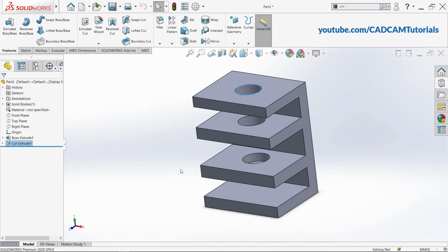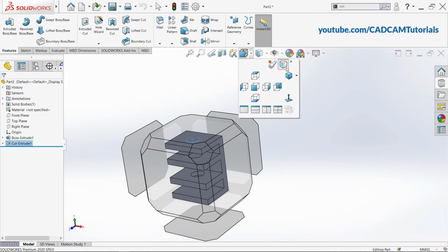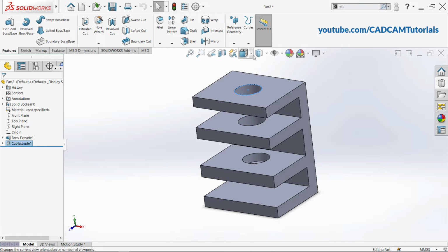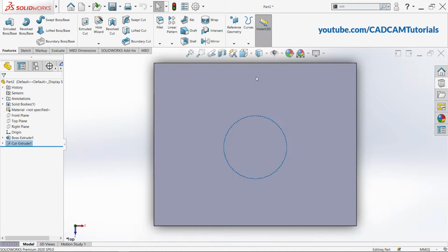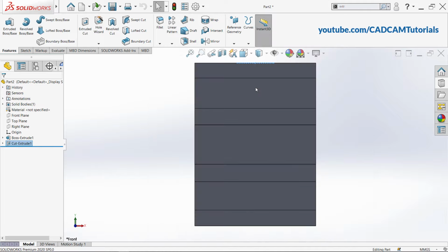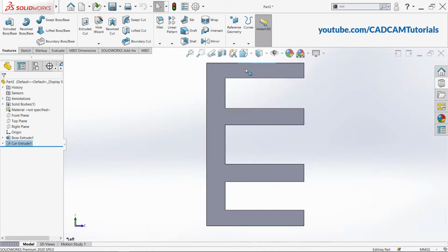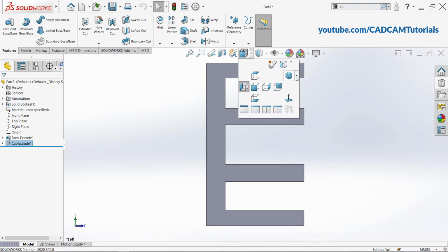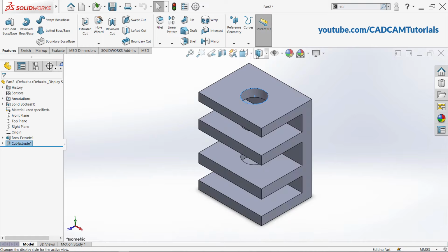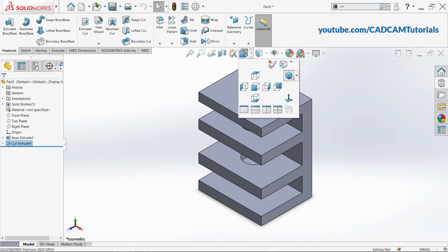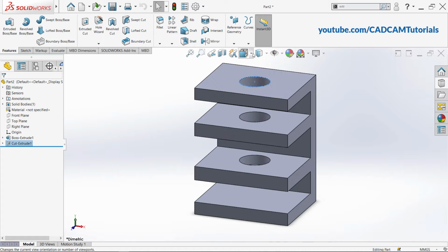And if you don't want to use that view selector, then you will have to click here and click here on this option here, view selector. Or you can also use Ctrl plus spacebar as a shortcut key. So just click there. So that view selector will not be displayed now. Then from here you can select different views, top view, front view, side view, or here are different isometric view, then dimetric and trimetric.